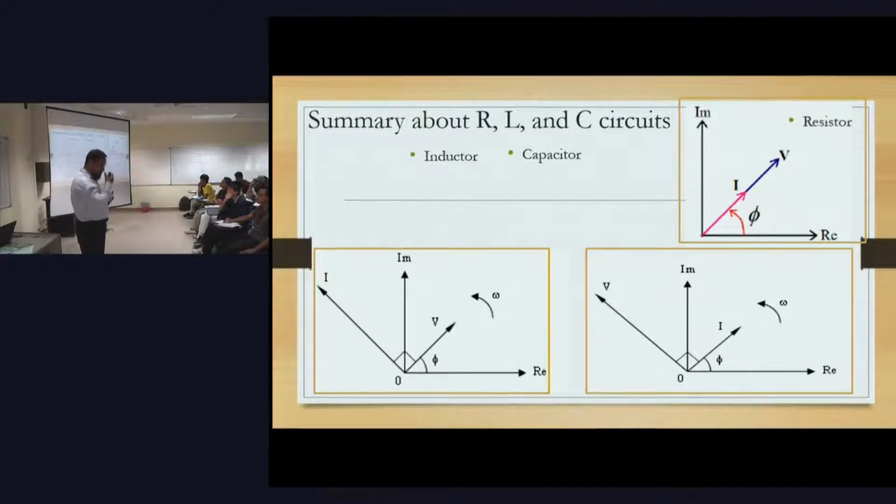And in terms of phasor, how could you represent this voltage? V with an angle of phi. Remember, the angle of a phasor you always get from the cosine representation. Please make sure you don't do it in the sine representation or as a function of sine. All right, so what do you see here? What is the angle for I, in the case of resistors?